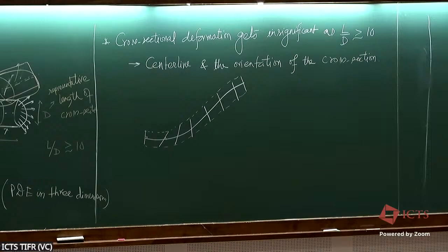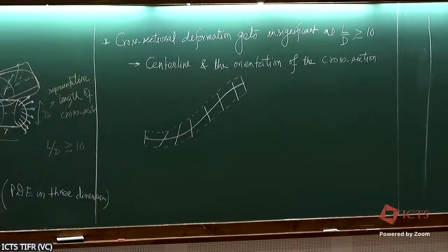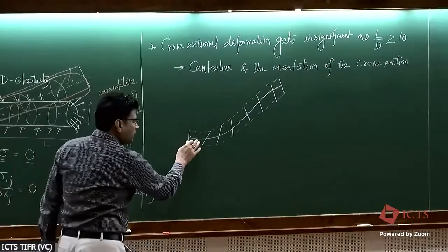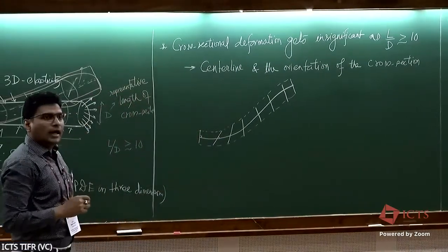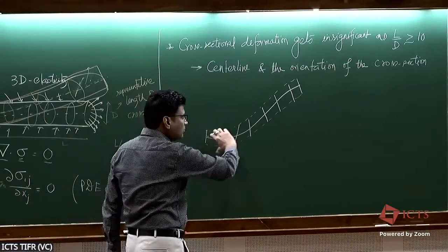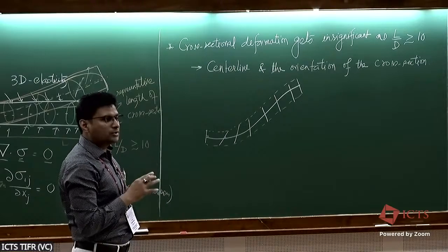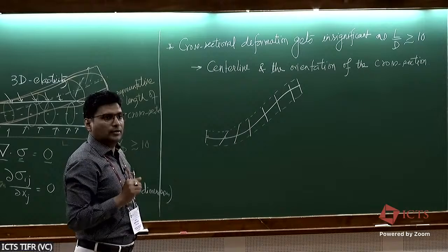So that's the deformed shape of the beam, approximate deformed shape, which turns out it does a pretty good job compared to the actual shape, the orange line. It turns out when you actually get your equations for just the center line and the cross-section orientation and construct your deformed shape in this way, it matches with the actual deformed shape to a very small error.